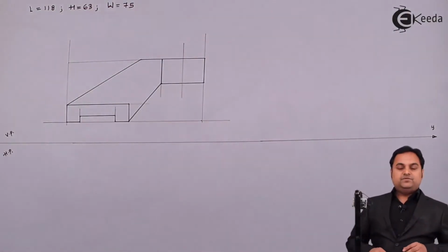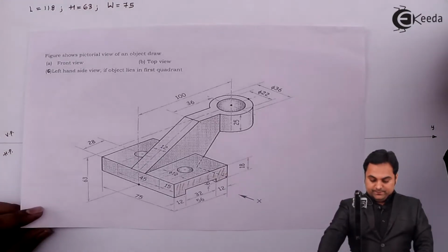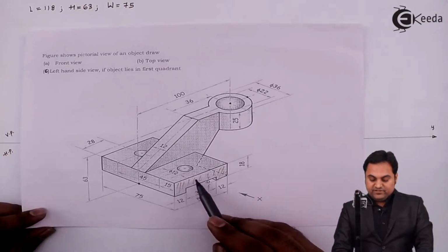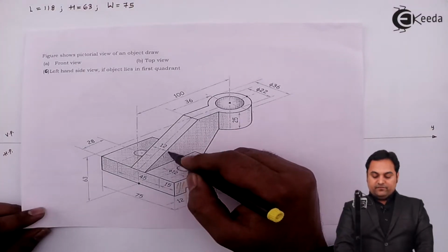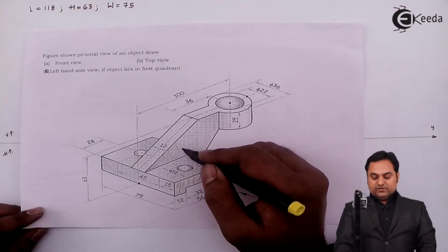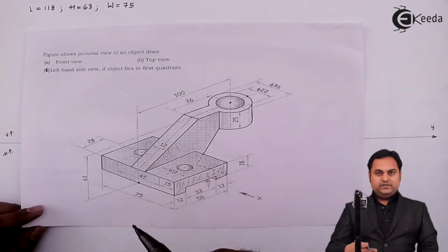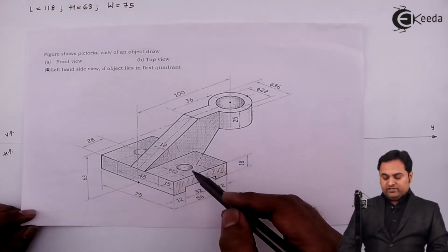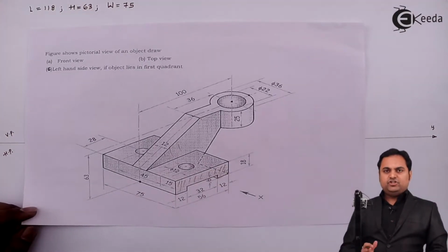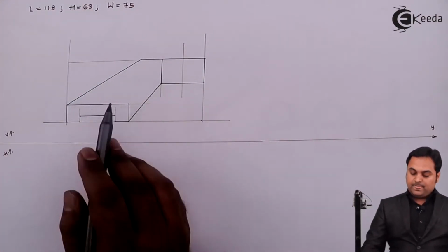So this much part is visible from the front, and when we are looking from the front view, this surface which I have shaded and this surface which is behind, they are not on the same plane because this portion is ahead, this is behind. So to show that they are different surfaces, meaning there is a change of plane between them, we have a dark line here.